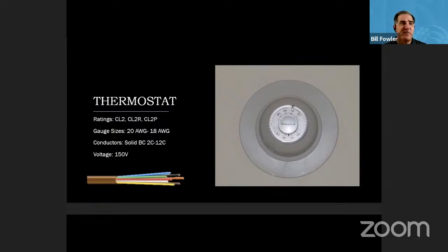So we saw the cable count go up in this thermostat wire from what traditionally you would see used in residentials. A lot of commercial we're seeing now requires an 8 conductor and a 10 conductor cable, and a lot of these new HVAC systems have a lot of electronics on the unit that want to communicate down to the thermostat, adjusting humidity, all that kind of stuff, monitoring all kinds of different systems at that access point.